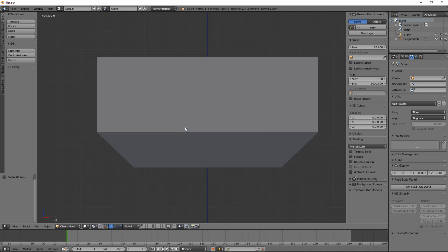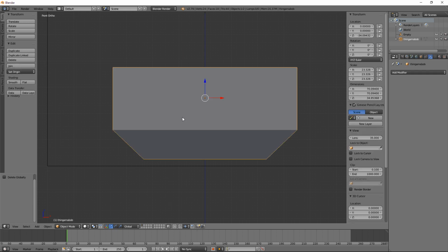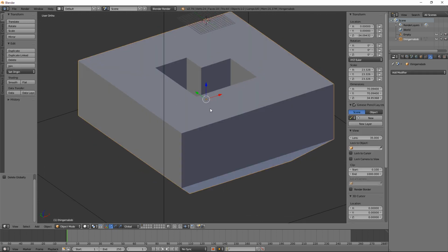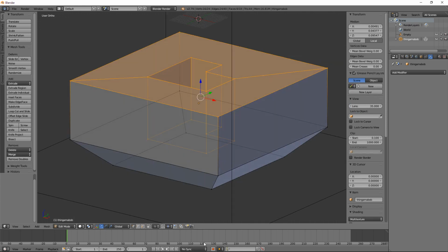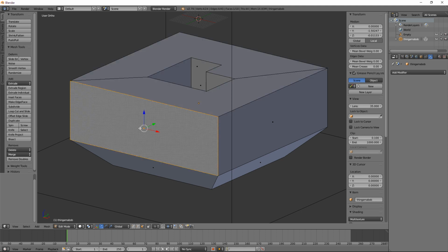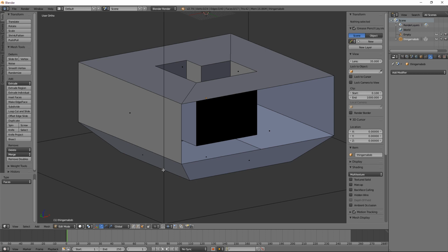Another thing we could do here, we could add more shapes, whether they're curves or other objects, and print them all. You could also, for example, if you've got a model that you've brought in that's not watertight or airtight, let's say it was missing a face. I'll delete that face just to show you this. It had an open hole in it that you needed to fill in. This is really common if you've imported a model and it's just not airtight. We'll want to fill that in.